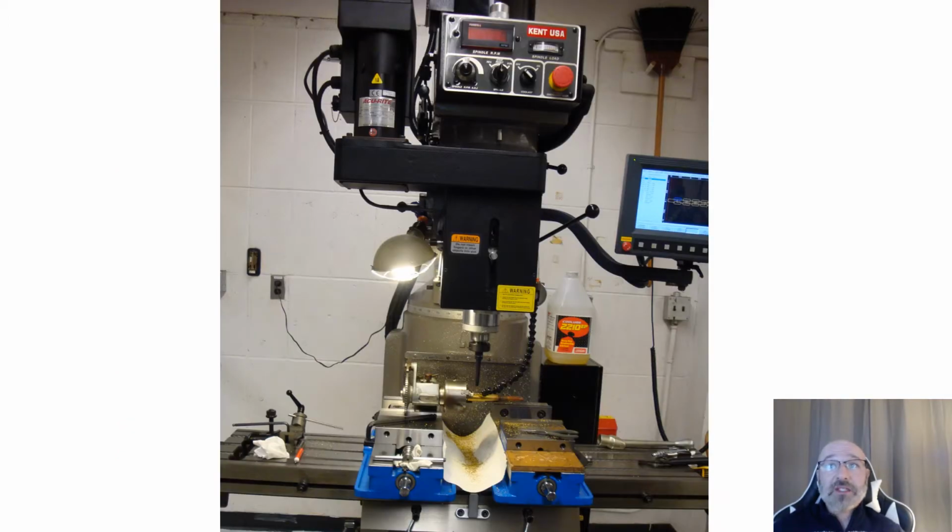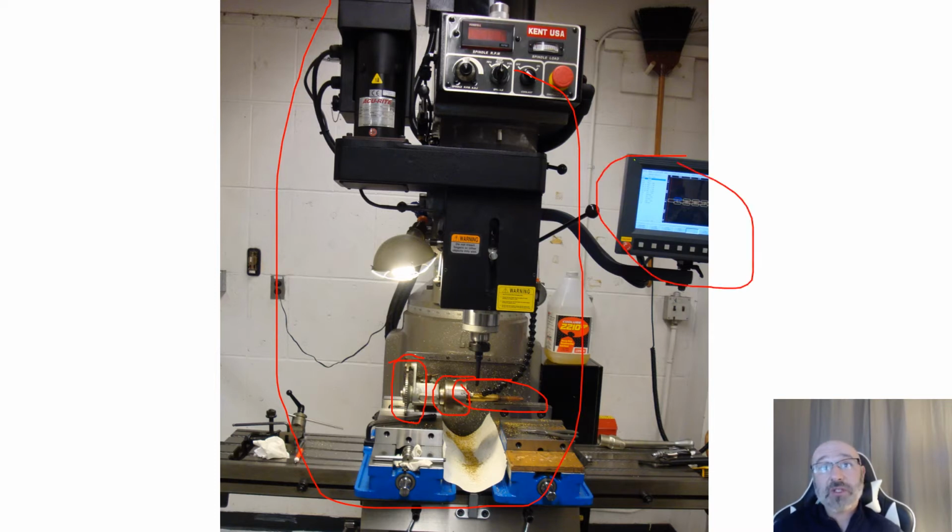So within this, again, this is a programmable CNC machine. This is a big, you can see now a zoomed out view here, see how large this actual machine was. Now we were looking at before, there's our little chuck mount right there. There's our 50 cal casing right there. And again, you can see over here on the side, we have this little apparatus here so we could rotate this as we're doing machining. And this is a programmable CNC. So what we needed to do was go in and actually program. You can see a little bit right here of where those dog bone specimens are programmed in now on the CNC machine there. And we'll get into a little bit more of that coding that we needed to do in order to obtain the correct size dog bone specimens for our tensile testing.